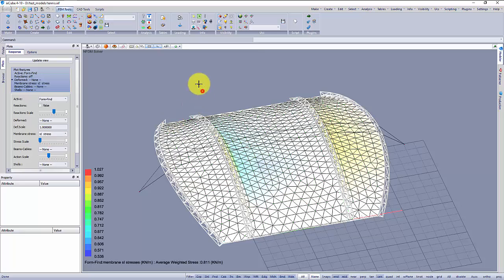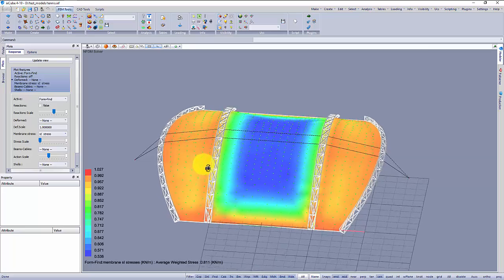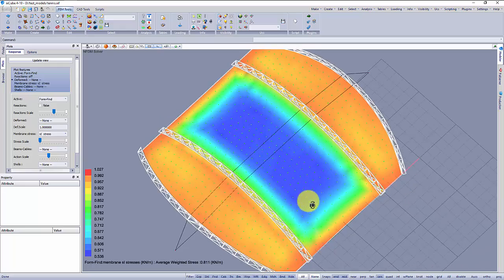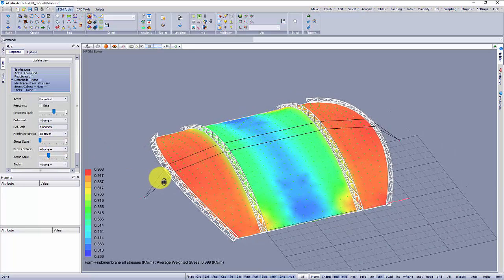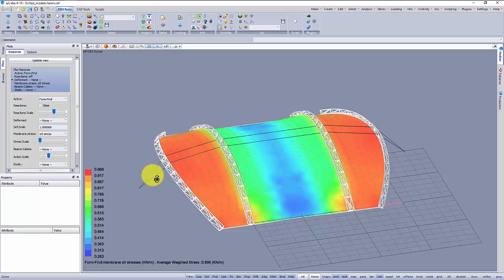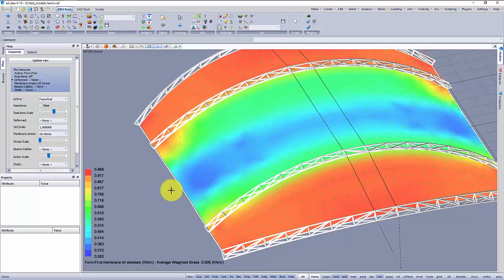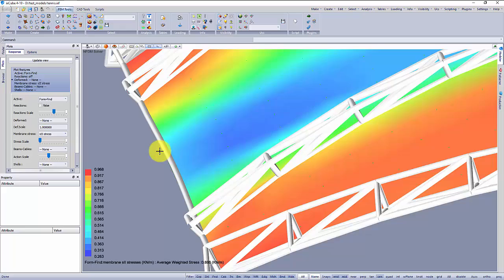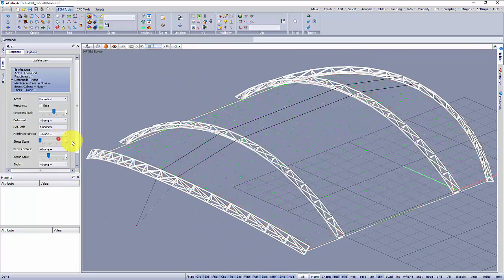and now you can go into the plots and give a look at the membrane stresses, and we see the membrane stresses. Oh, this has lost a little bit of pre-stress here. The middle membrane has lost pre-stress. This beam element is quite low stiffness, so it has bent. Anyway, for the sake of this example, it's okay.